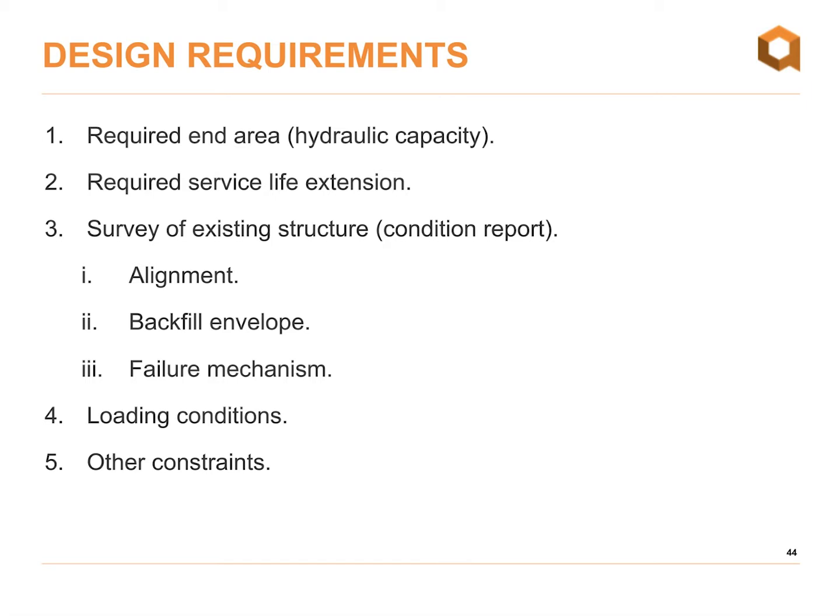We need to know the required end area, so what kind of hydraulic capacity is required for the new structure. What kind of service life do we need to design for as well? Ideally, we'd like to know the chemistry of the existing water course and of the soil as well, if available, so that we can accurately design for a given service life.